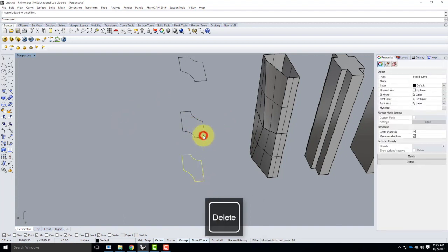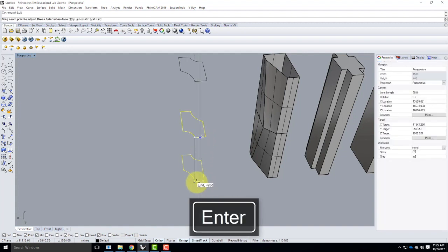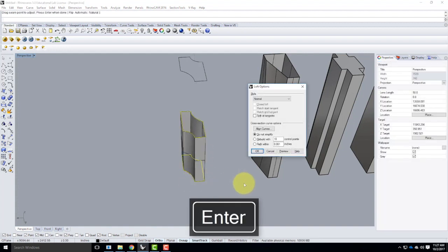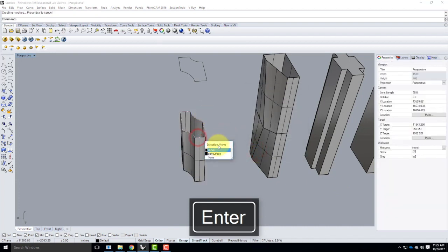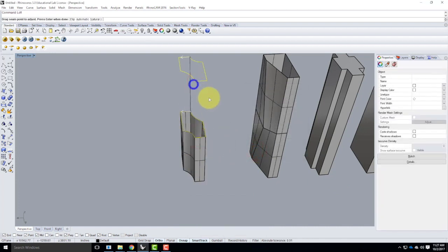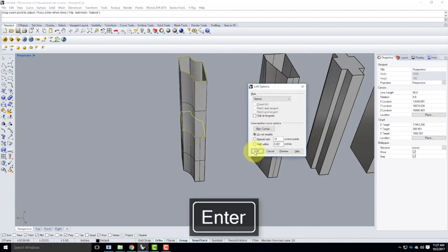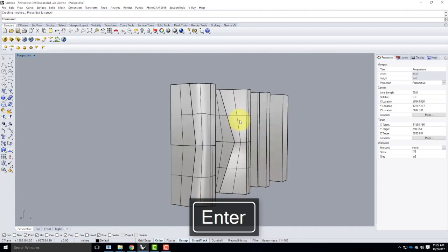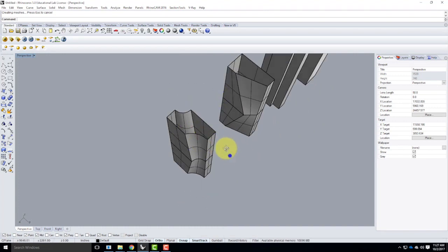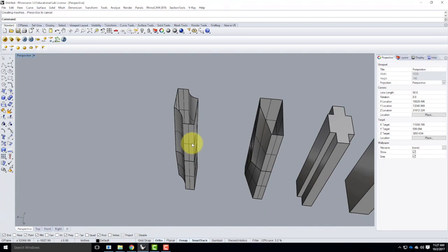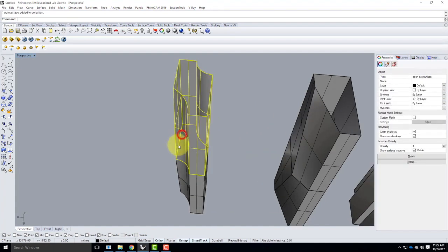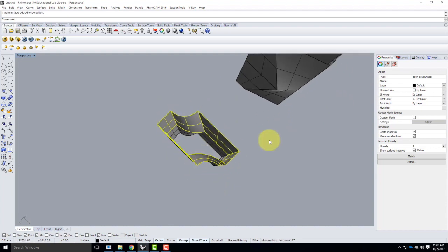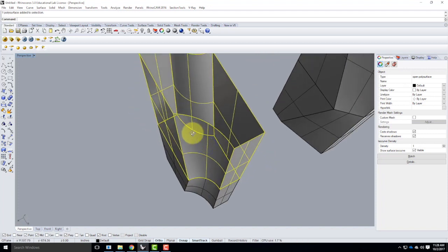And then I could take the first two here, and I could loft. Make sure that these 2 points line up correctly, which they do. And then I could take this and that, and again, I could loft it there as well. So in this case, similar in shape, but this time it has a curving profile instead of a straight profile. So just another strategy, something else that we can create. This one's going to be hard because it's not going to develop the same way that something like this was. We're not going to be able to unroll it. So long term, as part of your assignment, I'm going to ask you to unroll it. So this is less than ideal for the long term. But in terms of today and exploring what you're doing, by all means.